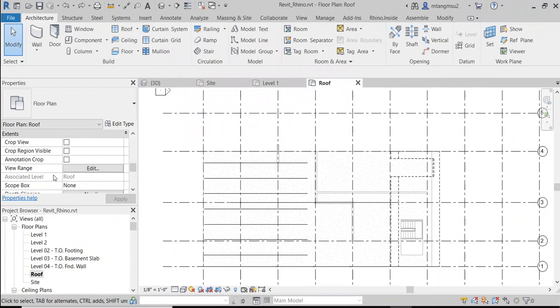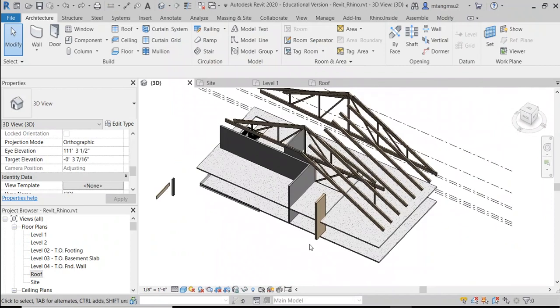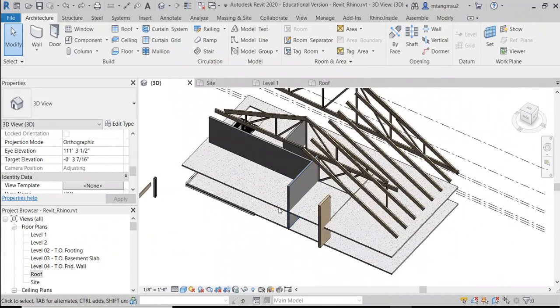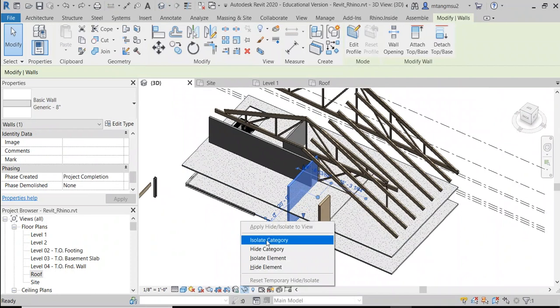Okay, so this is another part. The visibility will make some confusion. And here's another part. You might temporarily hide objects. So here in Revit, if you click this glasses, you can hide. You can choose either hide category or you can hide elements, right, from the glasses.